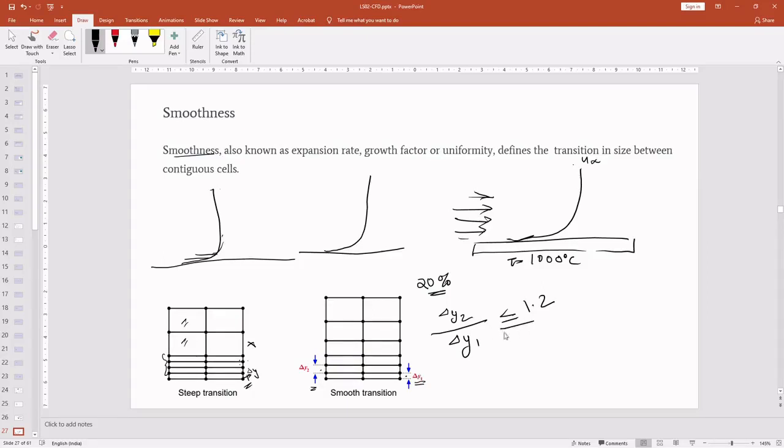So this is somewhat an ideal condition. So we have to keep this kind of growth rates. But here you would be seeing, this is only for a two-dimensional thing. So this thing applies for 3D as well. Also, if we are using some triangle elements, suppose we are using some small triangles, so this is a larger one, this smaller one. This transition should be smooth.